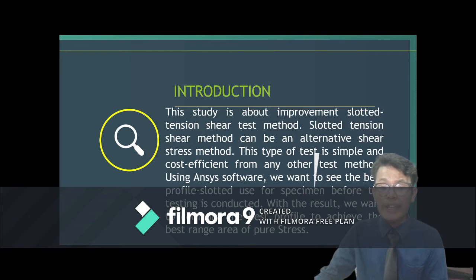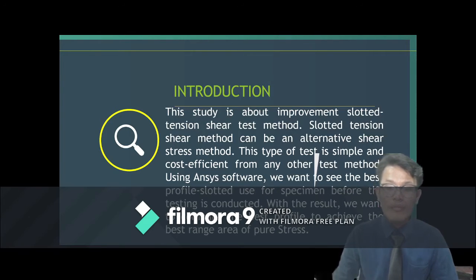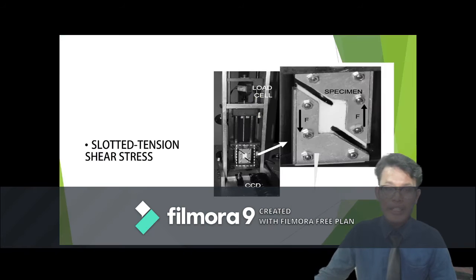By using ANSYS software, we want to see the best slotted profile for the specimen before testing is conducted. With the result, we want to compare the profiles to achieve the best range of shear stress. Here are examples of the slotted tension shear specimens performed in the lab.